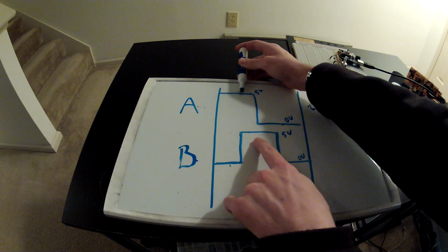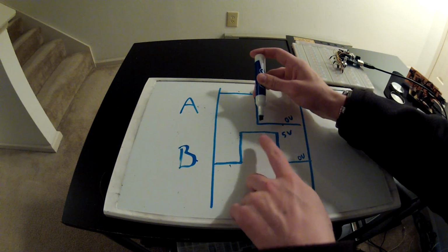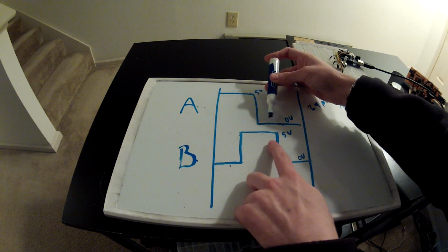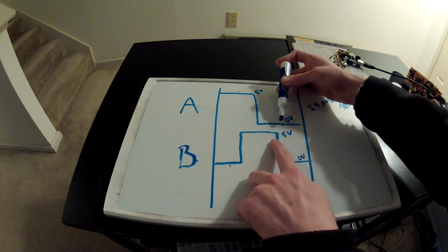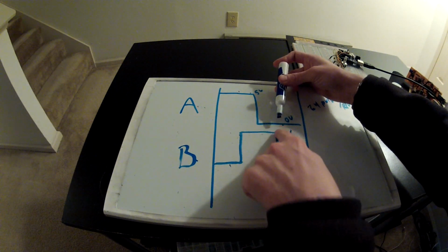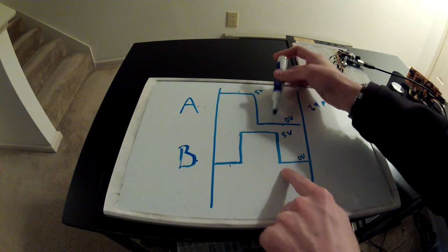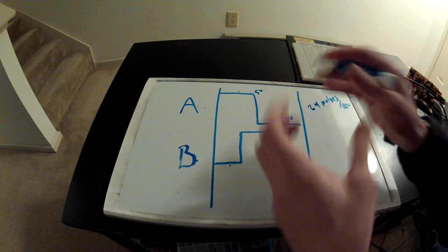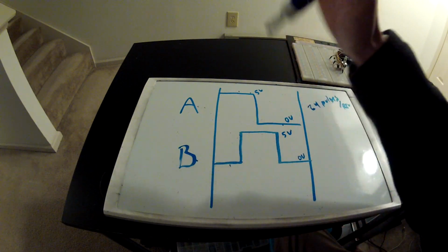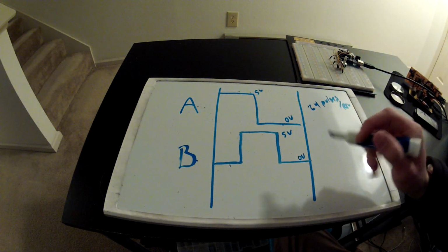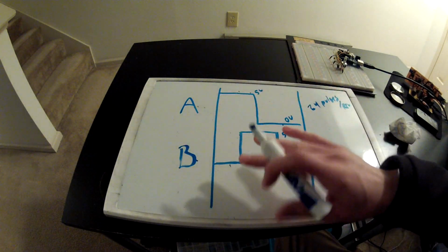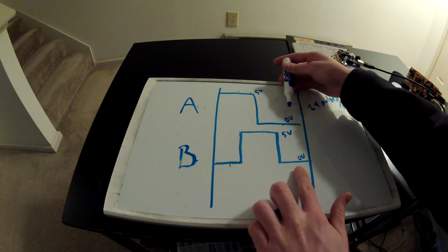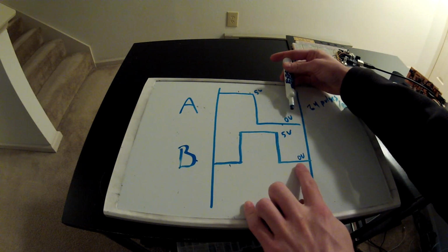You continue to rotate on. The A signal falls while the B signal is still high. That means we're rotating forward. Okay, and you just keep going through it, and then all of a sudden you get a change in the B signal from high to low while the A signal is still low. That means we're moving forward. So you code all this into your code so that you understand exactly which direction. And so you have all these different states that it could be in, and then depending on which event happens and what the other signal is at, you can determine direction. Because if you move the other way now, B signal is low, A signal is low.